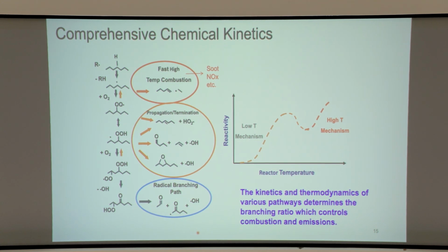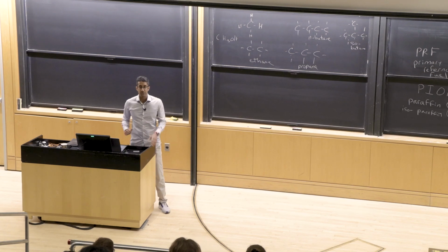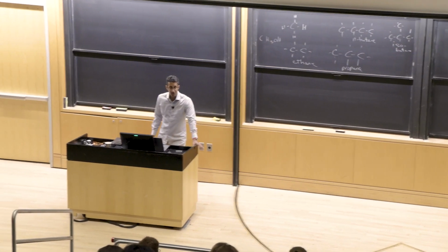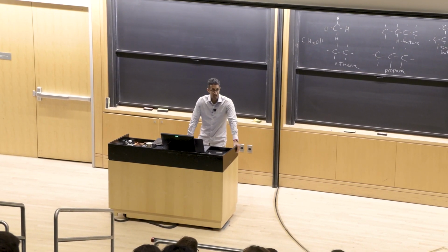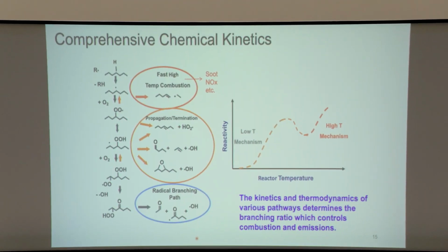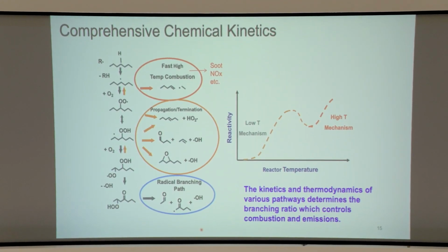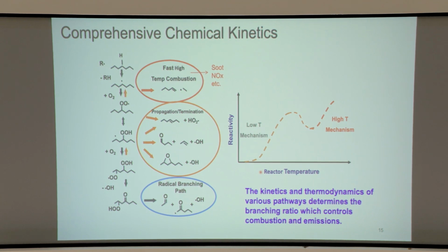It's trying to propagate upstream, so it's preheating the reactants upstream maybe by a few hundred degrees Kelvin. So they're starting to undergo high temperature reactions already. Any type of flame is a high temperature combustion phenomenon. You don't care about low temperature combustion. When do you care about low temperature combustion?